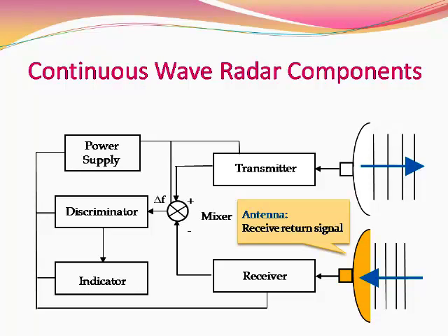The antenna is going to be a normal parabolic dish if it is going to be a microwave frequency operation. If it is a low frequency operation, then we may consider a horn antenna or similar things. But definitely it's going to have some sort of directionality to see that the power is concentrated towards the target expected direction. Similarly, the receiving antenna is also going to be a parabolic dish or a horn antenna or similar directional antenna. Here, the received signal is normally very low, and to have a good output signal from the receiving system, the effective aperture must be large. So in that sense, a directional antenna is preferred in the receiving case also.